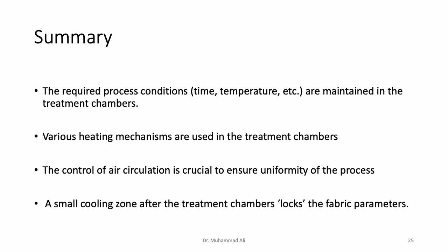There is a small cooling zone after the treatment chambers. From the point of view of design of the machine, it's fairly insignificant, but the role of this cooling zone is very important, because the fabric that leaves the treatment chambers has to be brought below the processing temperature so that the fabric parameters are locked in place.